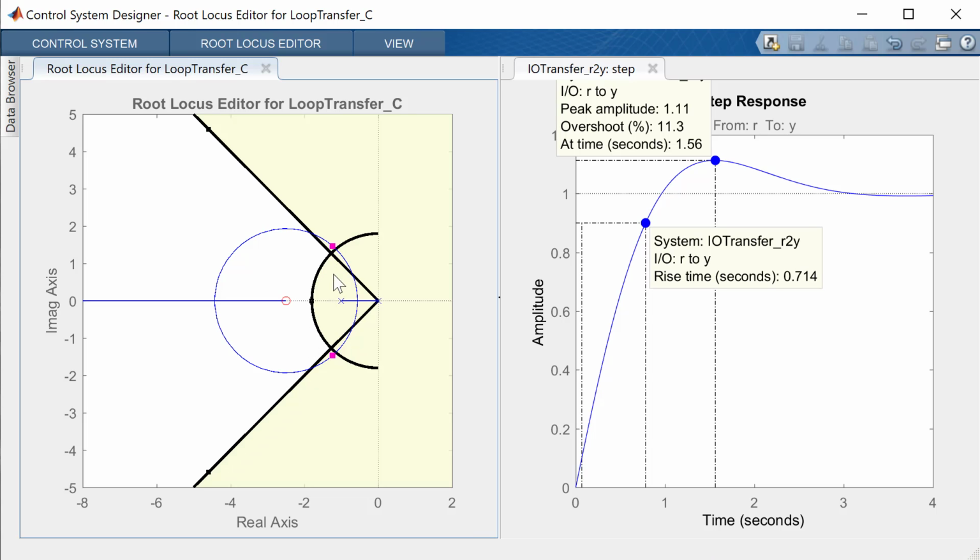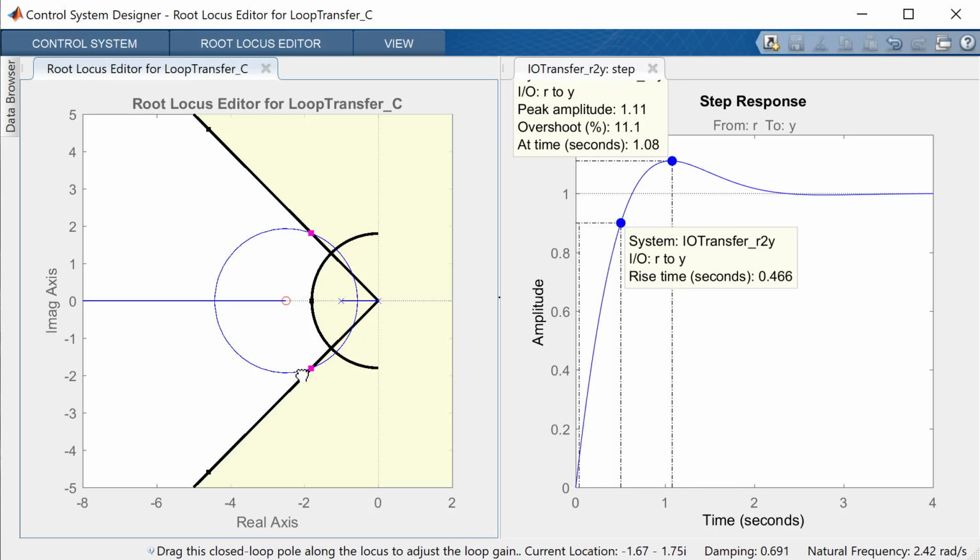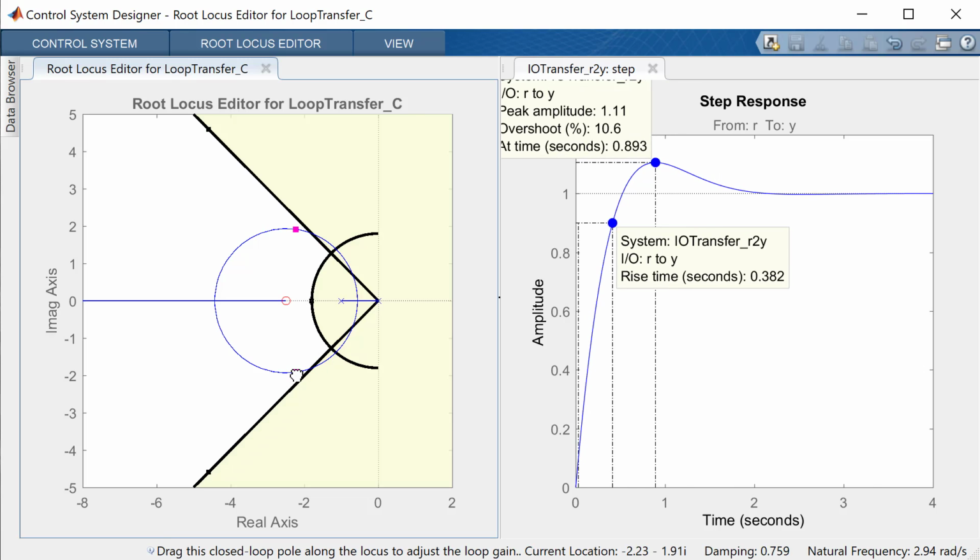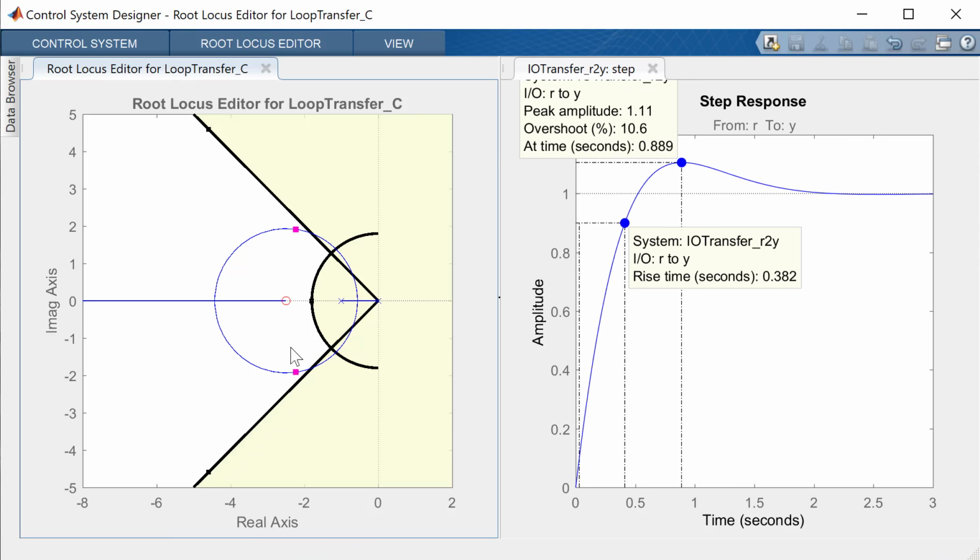And now you see we've moved the root locus to a point where there is a value where you can get these poles into a position that satisfies our time domain specs. In this case, this is no longer a simple second order system, so this is merely, again, going to be an approximation, but it's going to inform our design criteria and our design choices in a directionally correct way.